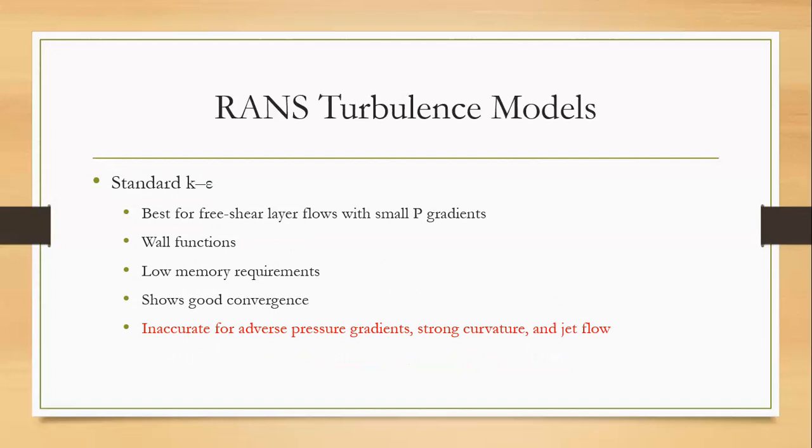And yes, there are wall functions implemented. That means near the wall, you can keep the y plus value between 30 and 100. If you keep that value, then you'll find that you need fewer elements in your domain. And consequently, if you keep your y plus value between 1 and 30, you will find that the number of elements needed will be much higher. Okay, we will see that in our practical example as well.